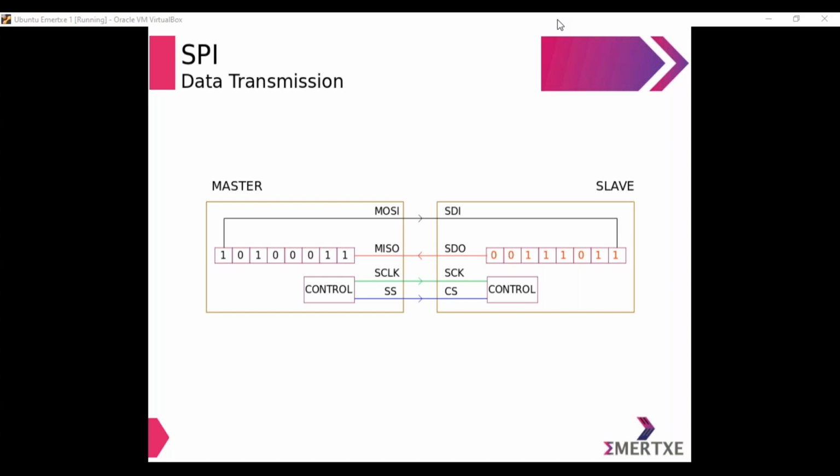So here also the same thing happens. First, whatever data I want to transmit should be written into the buffer register. From the buffer register, data gets written to the shift register. From the shift register, data gets shifted bit by bit. Now assume the master has the data 0xA3: 1010 is A and 0011 is 3, right? So assume the master has 0xA3 to be given to a particular slave. First this data gets written to the buffer register.